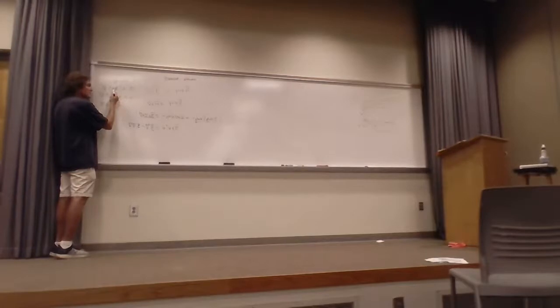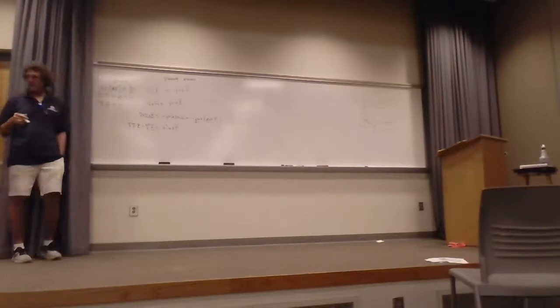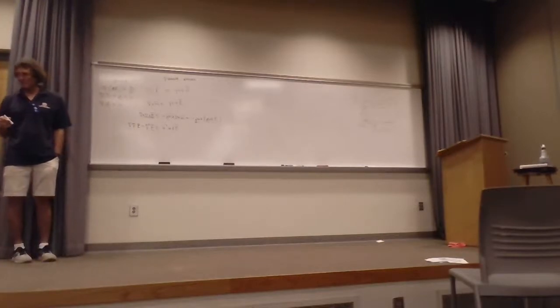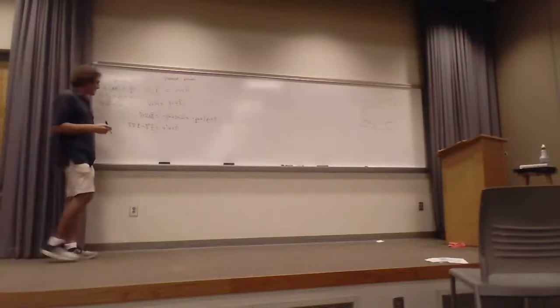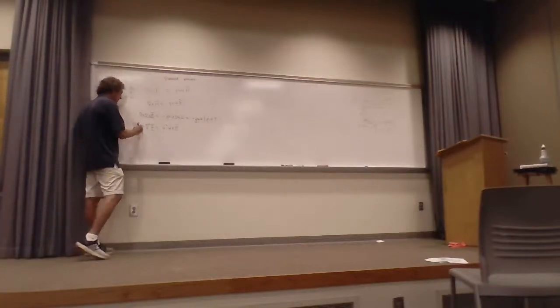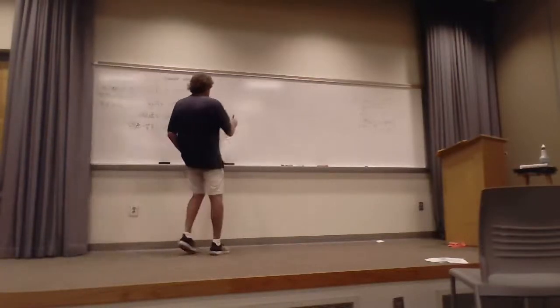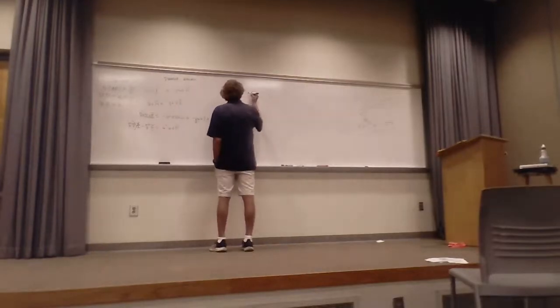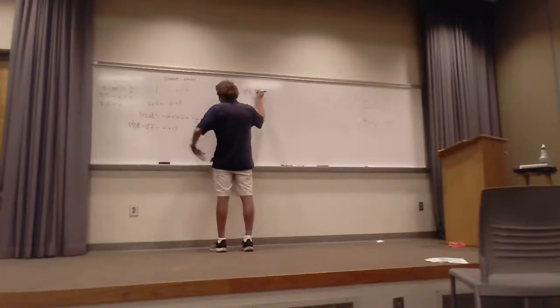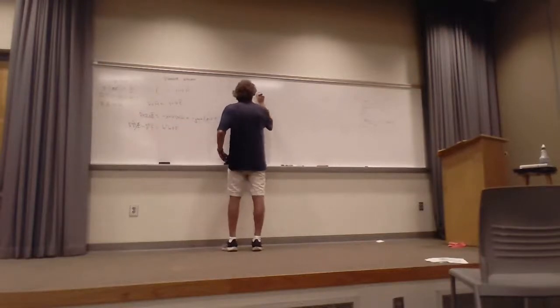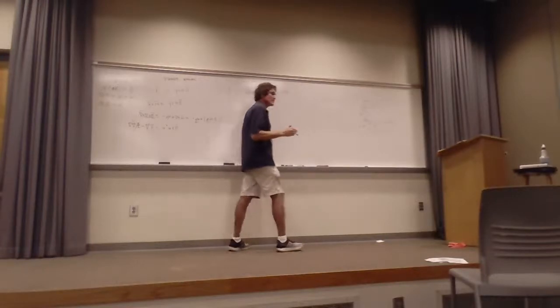And assuming epsilon is not something that spatially varies, then it would be 1 over epsilon, or divergence of E is 0. Okay, everyone? All right, that means this one goes away, and I have del squared of E. And if I take this to the other side, it would be plus omega squared mu epsilon E is equal to 0. That's true inside the guide.